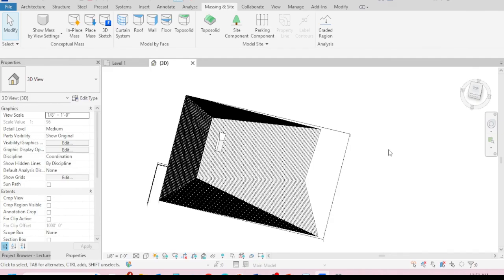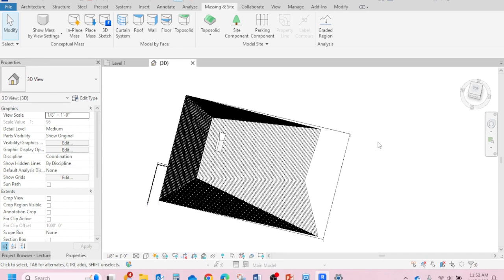Now you may have created and placed the 23-foot by 70-foot concrete back into the hillside, but it still looks really low. So that the floor level is not this far down in my topography, I'm going to lower the topography to maintain the level 0 of my building pad.